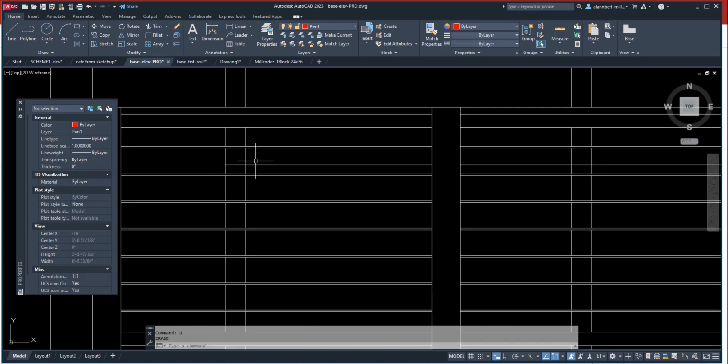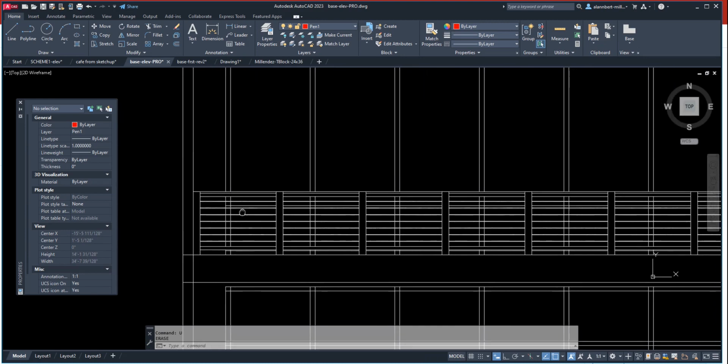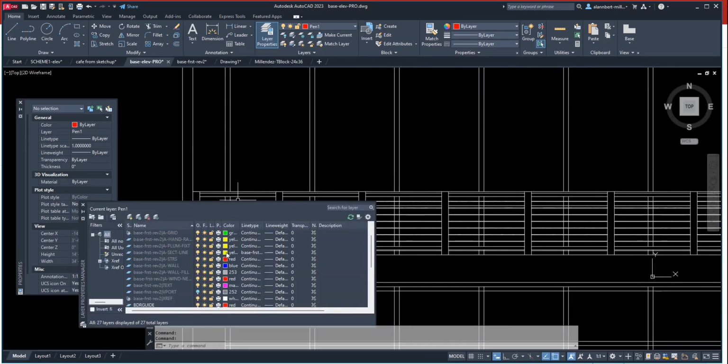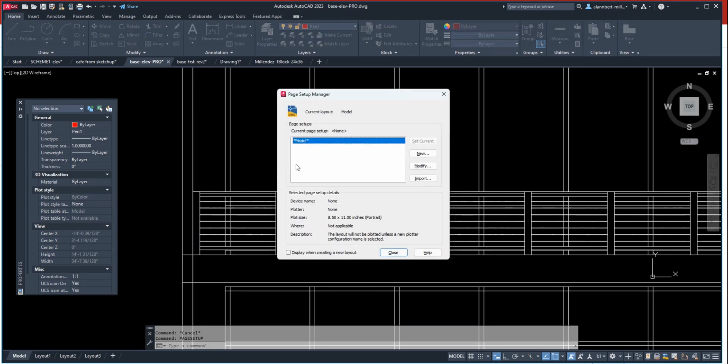And what we can do is we can assign them into a different pen color. So let's do a layer, and let's see if we have already pen 252. Ah, there it is, pen 252. Now, I'm just curious, what did we assign our 252 thickness?